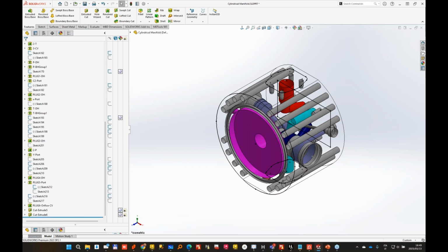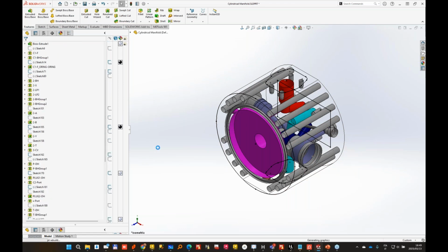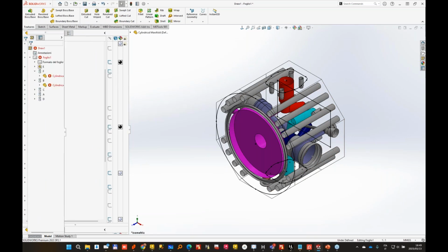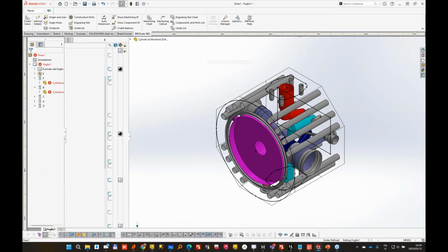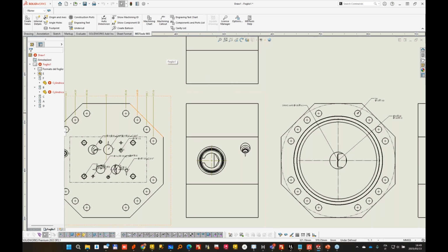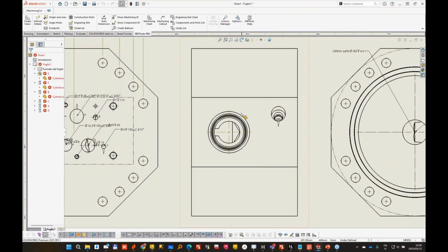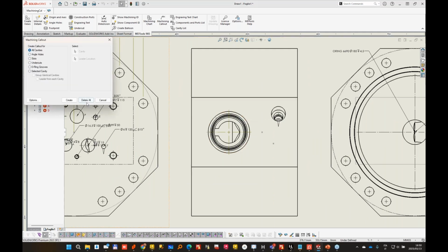If you just move the end of the part slightly up and you leave the faces, then it will be possible to display all the machining callouts, even if now you have the octagon, but that's temporary. You run the machining callout. This will work for all the cavities, also for the ones that were missing.